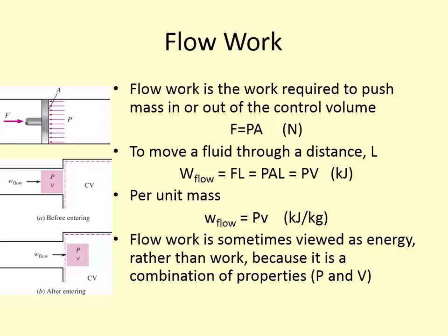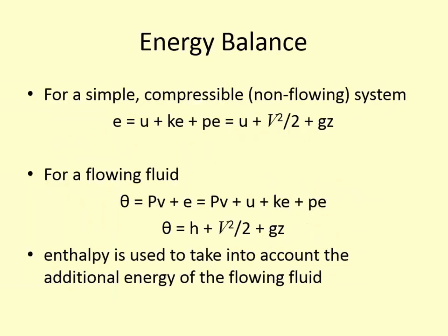So previously when we talked about the difference between heat and work and energy, energy can be possessed by a system, but work and heat are not defined properties of a system, whereas flow energy, we kind of can define it as a property of this system because it's a combination of property values. So regardless, the units on it are units of energy, so whether we look at it as a work or an energy term, it really doesn't matter as long as we analyze it correctly.